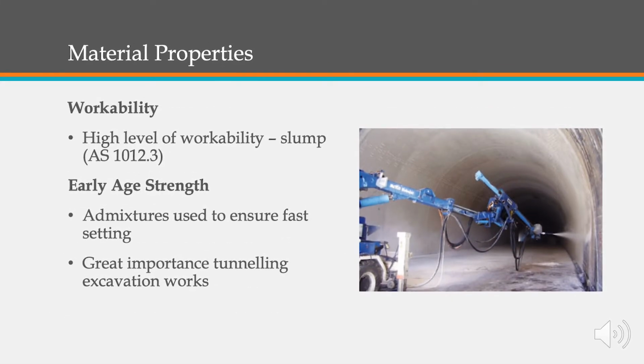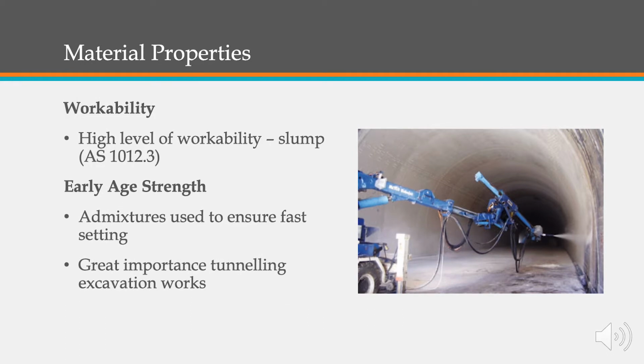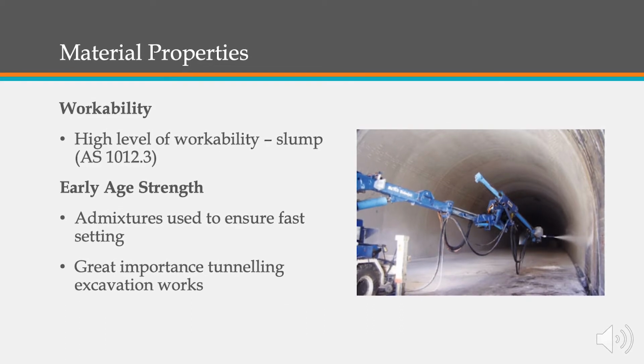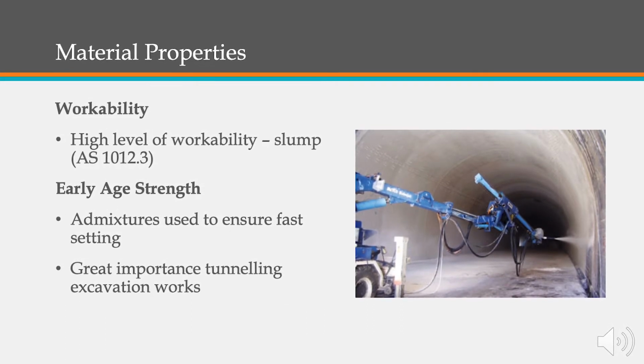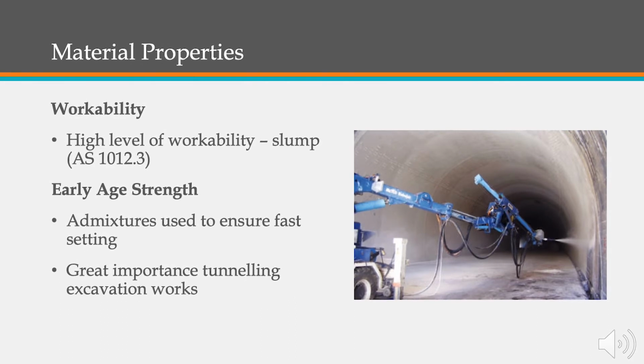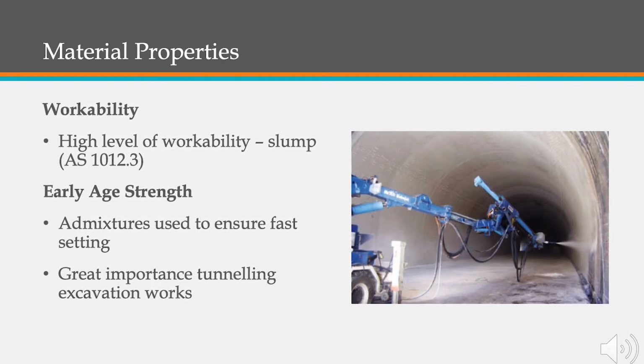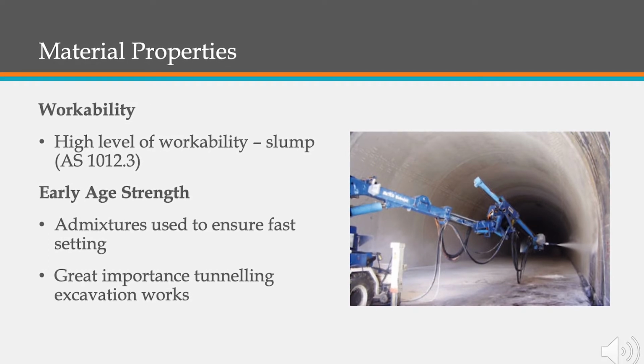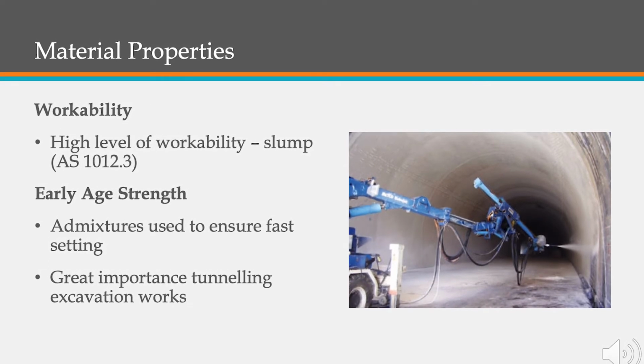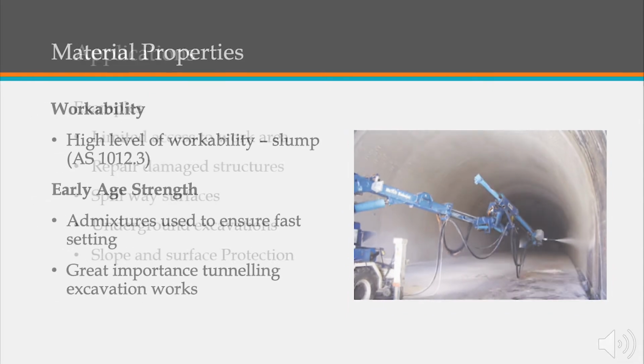Shotcrete has a very high level of workability, as indicated by the slump test. This is so that it can be more efficiently sprayed. It's important that shotcrete mixes exhibit high early age strength so that it holds shape where it is applied and so that structural support can be quickly added to the area of application.